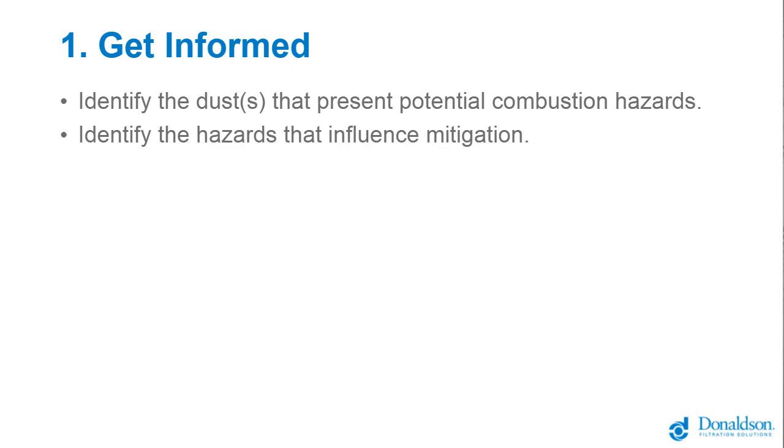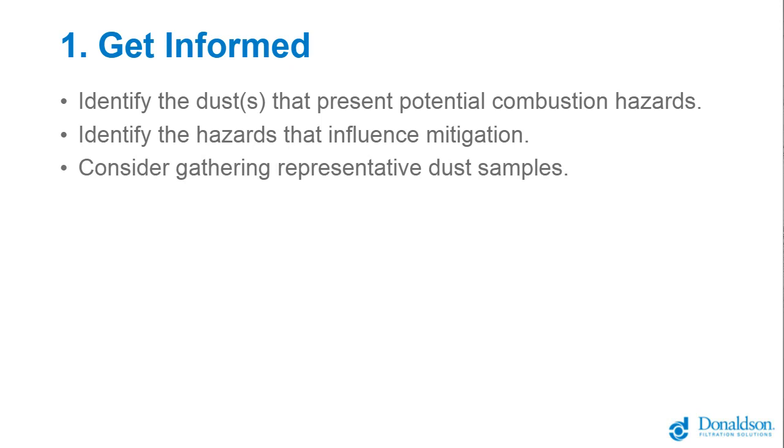Obtaining accurate information on the actual hazard characteristics of the dust is very important. The outcome of this data often has a direct influence on the selection of mitigation strategies. Prior to submitting dust for testing, ensure the samples are highly representative of the dust present in the process. Samples should reflect the physical characteristics likely to produce the most risk. When different dusts are blended, samples should also represent the most likely combination of mixed material.